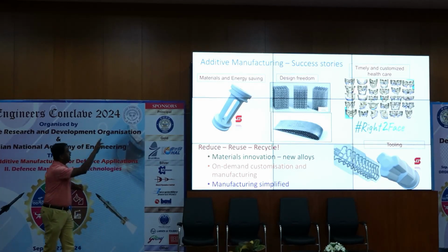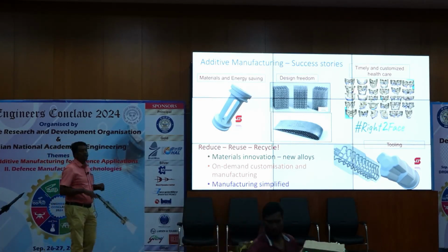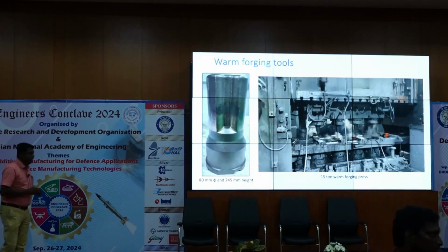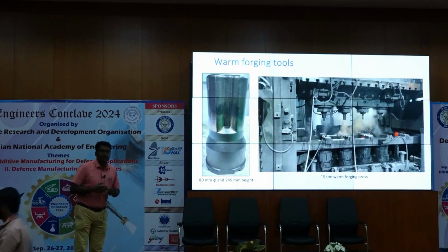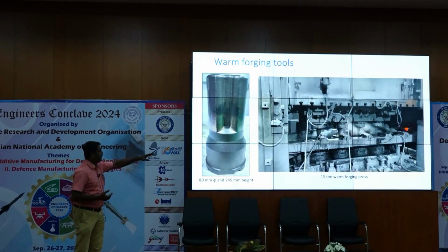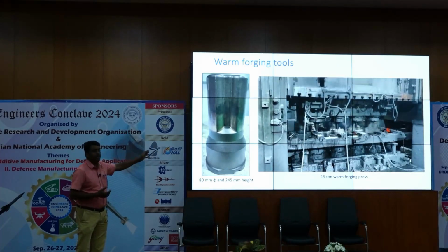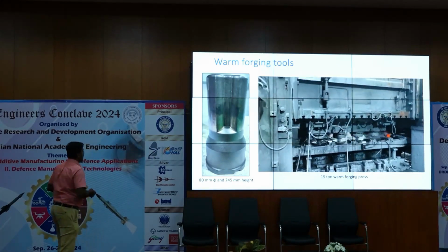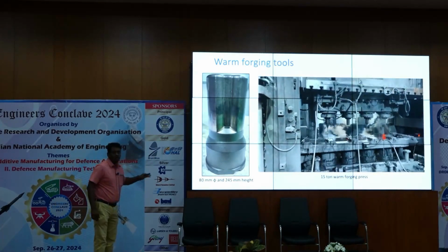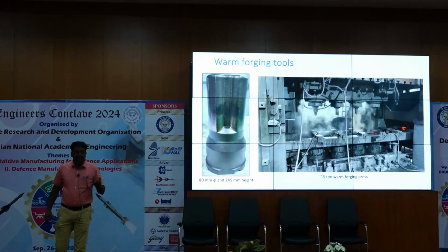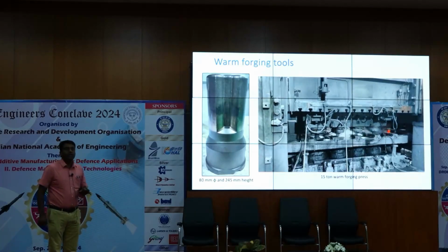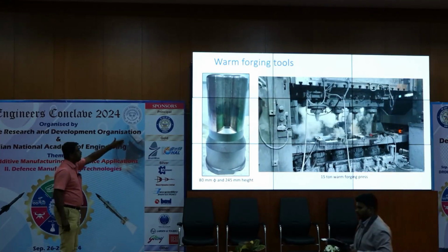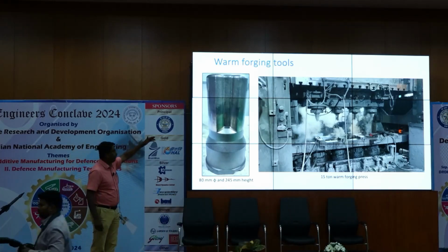Right, I'll show a couple of stories, starting from the extreme left, with the tooling, what we have done at IIT Madras. If you look at forging tooling to produce end-use automotive components, the components you see here are forged in multi-stage forging. The punch used in this forging application is made using H13 or M2 steel, and the life of these punches is extremely poor. The load applied on these punches is tremendous. In this case, what you see here is a 15-ton press used at Product Forge.